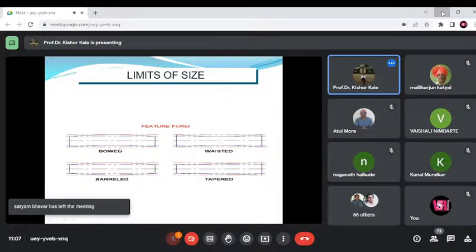As you know, not every GD&T feature requires a datum. For flatness, we don't require a datum. We have already seen that these four don't require a datum. This may or may not require one, and all of these require a datum compulsorily. Now here, the base of this part is datum A, and this is datum B. So this indicates the A surface.